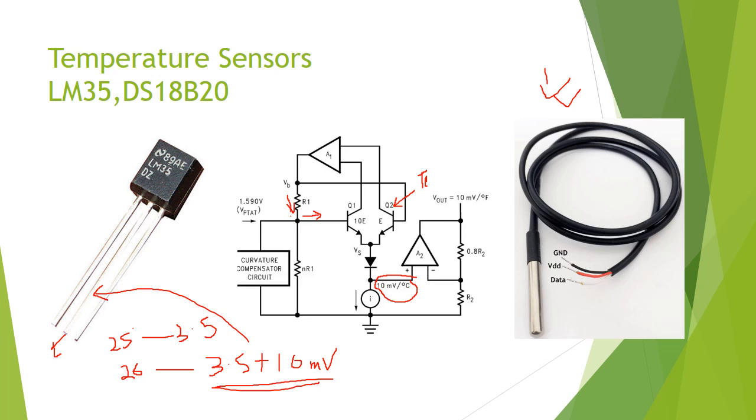So you will use this type of temperature sensor, the DS18B20. The LM35 will not work in fluid, so this is more complex. Suppose you want to measure the temperature of the soil, then you need to use the DS18B20. So this is the difference between these two.